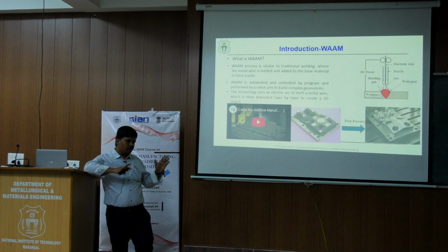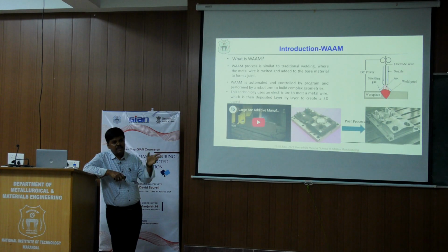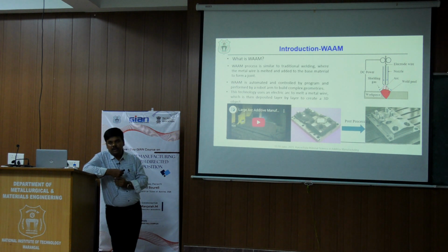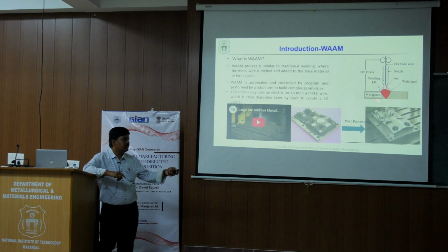But if you compare only wire arc with the laser wire DED process, laser wire DED is going to give good mechanical properties and good quality components, and even the post machining is minimal. If you use the wire arc manufacturing process, it is cost effective, but it additionally adds post machining aspects. That is what we have attempted in making such dies.